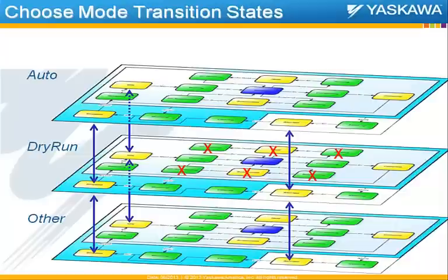And typically, you want to set them up at some condition where the machine is quiet. Some very common ones include aborted, stopped, or idle. These are states where the machine, first of all, is in a wait state. It's not doing anything. And they're also in a nice quiet condition. Maybe the servo axes are disabled, for instance. So freely definable. You can choose only one. You can choose many. You can choose to go anywhere from any place if you like, but usually limited to these 3.